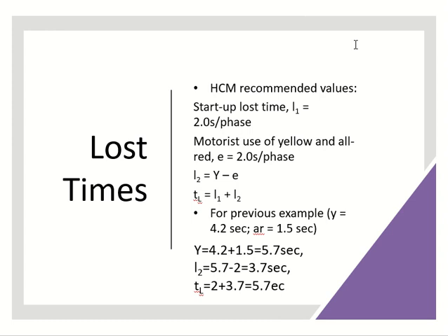So they did their study, they found that for them startup loss time is 2 seconds. You can do your own study using the headway and find out your own loss time. Startup loss time, done. We know how to do it and we know the value which we can use. Worst case scenario. Now, the other one is clearance loss time. We said clearance up to now, according to us, clearance means all red. Because all signals are red, that's loss time. Vehicles which have already entered are clearing the intersection.